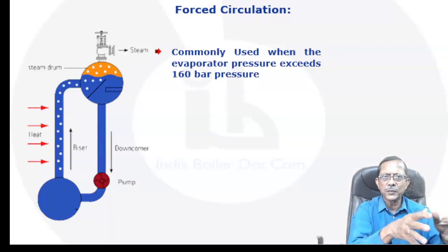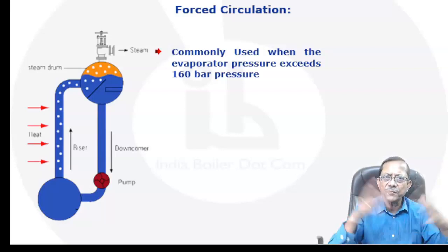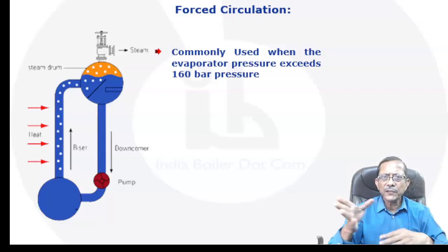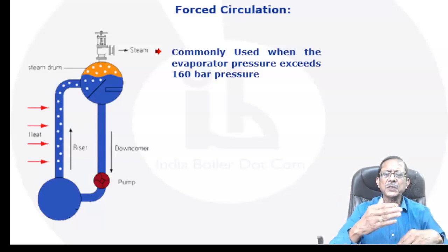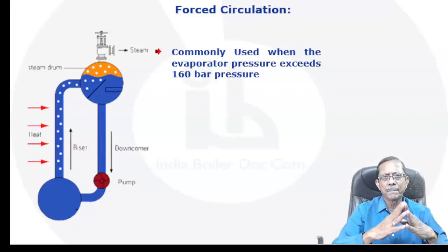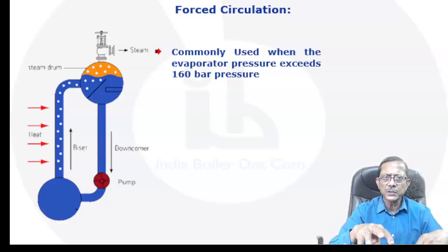The startup is for the process. So when the reactor is started, the exothermic reaction might release the heat at a very fast rate. And we have seen that during cold start, if the ramp up is not controlled, right? Because normally, gradually, if the pressure increases, the steam load increases, then the circulation will be created. So in such cases, we have a forced circulation system.